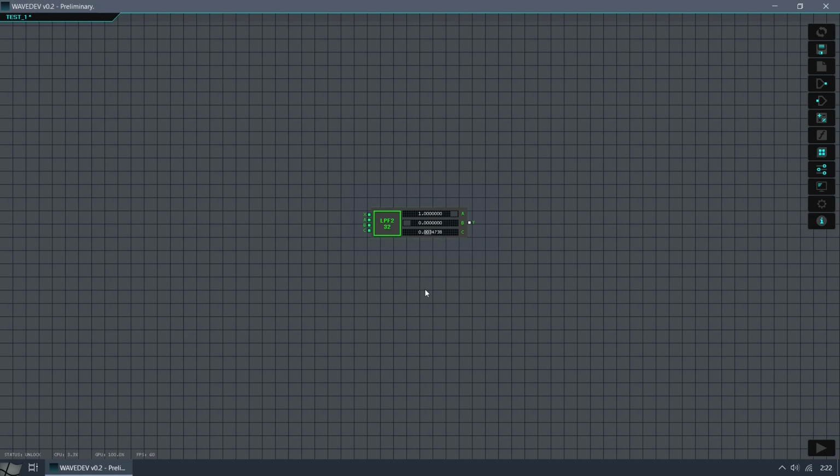So to know the selected frequency, we will have to use a temporal custom function here. As the name itself suggests, we can oscillate the filter with a simple impulse, setting the resonance to the maximum. By moving the bar towards the extremes, we can know the limitations of the filter. On the upper side we see that we reach 7.3 kHz. On the lower side, 13 Hz.